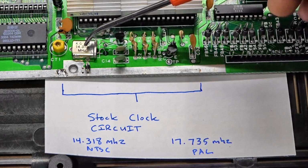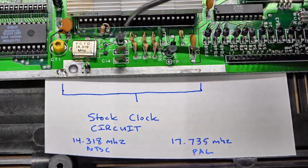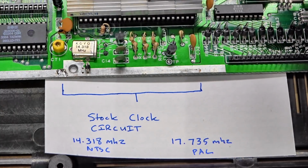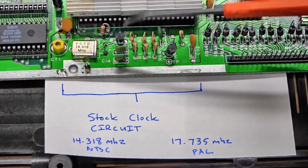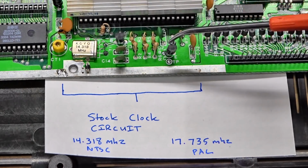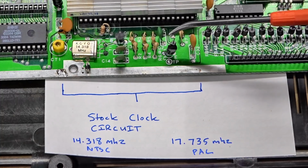Now this is a very simple crystal here, and you do need to have support circuitry to actually generate a 5-volt clock signal like the type the TED needs. And unfortunately, I need to bypass this entire circuitry. So to do that, I had to actually cut a couple traces on the bottom of the machine.